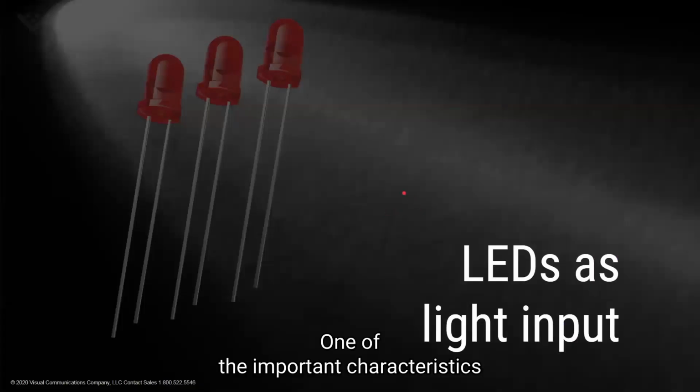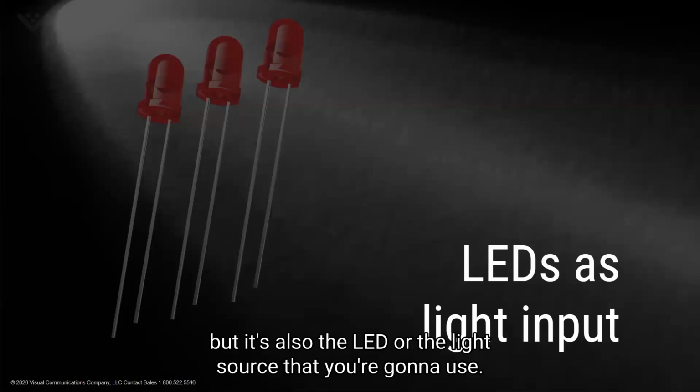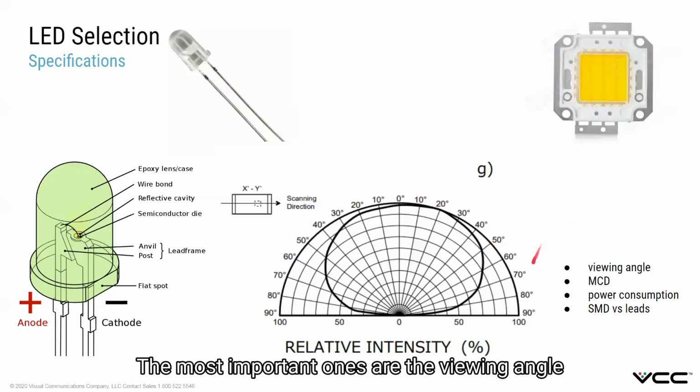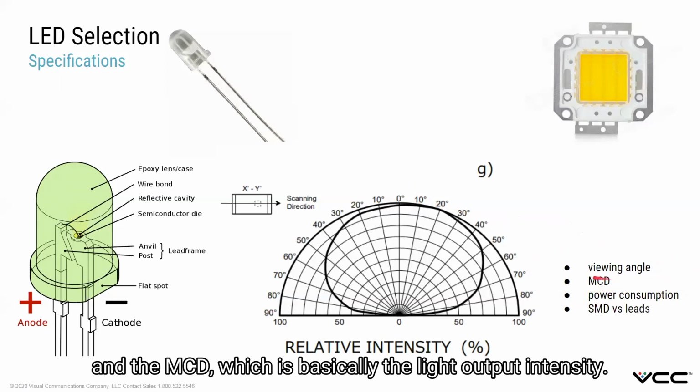One of the important characteristics for the light pipe to work is not just the light pipe itself, but also the LED or the light source that you're going to use. The reason is pretty simple. The most important ones are the viewing angle and the MCD, which is basically the light output intensity.